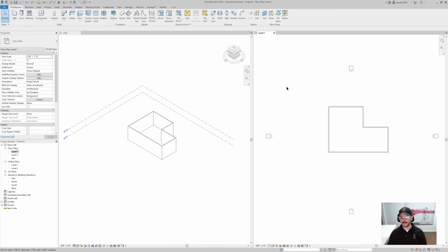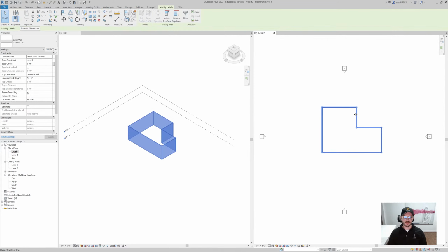If you select from left to right, the whole element will have to be within the bounding box for it to be selected, right? Or since this is a completed circuit here, I can just hit tab while I'm hovering over it, and it'll give me the option to select the entire chain, not circuit.